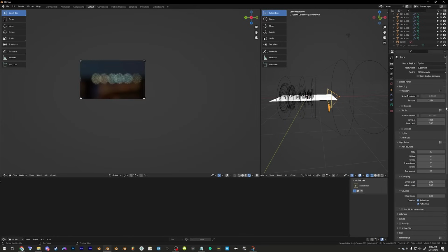I would like to increase my sampling. For things like this, you can increase the samples to like 20,000 while you're testing, and it would be completely fine. It renders very quickly, even on a mediocre GPU, since it's only processing light. It's not processing any actual bounces.